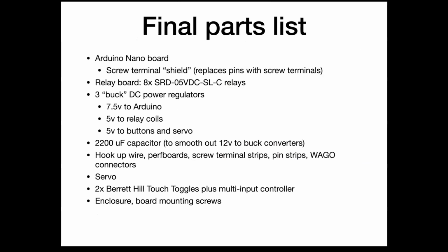I used an Arduino Nano, which is a nice small board. On top of it, there's a thing called a shield. And the shield provides little screw connectors instead of the normal pins. And this goes to the primary rule: if you can't make it perfect, make it adjustable. So I wanted to be able to fiddle around and learn and adjust things, and also to make it easy to replace something if I let out the magic smoke, which of course I did.